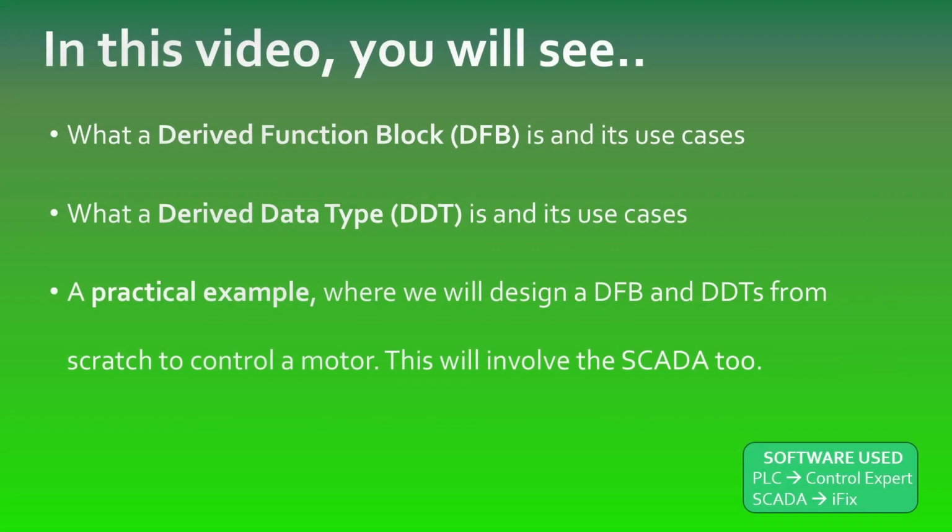Hello and welcome. In this video, we are going to see what a derived function block, or DFB, is and when it is recommended to use one. We will also see what is a derived data type and its use cases. Finally, we will do a practical example where we will design a DFB to control a motor along with the corresponding DDTs to facilitate control management.